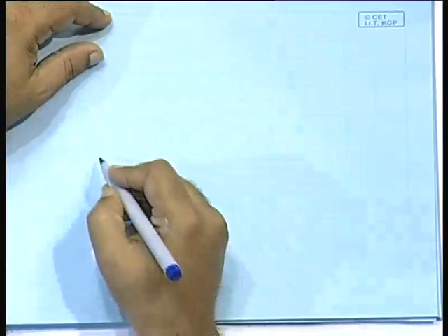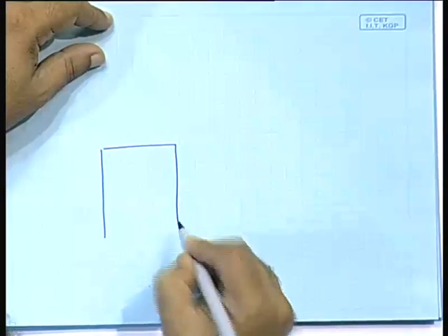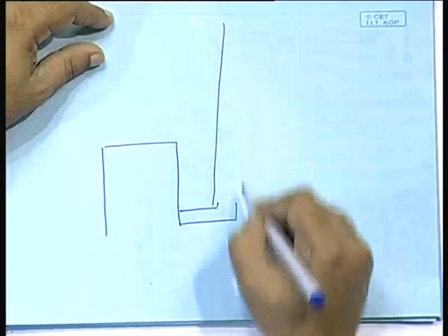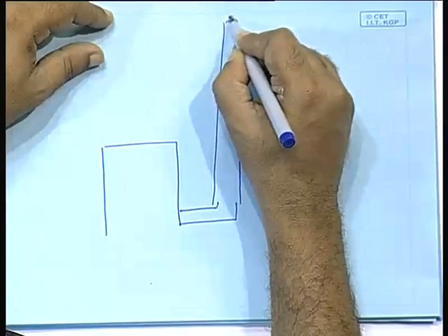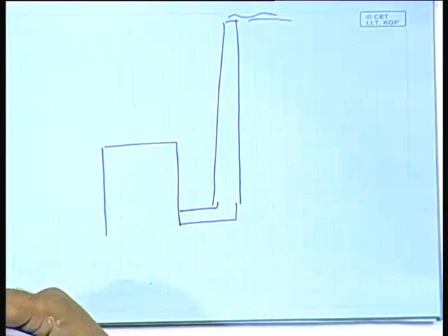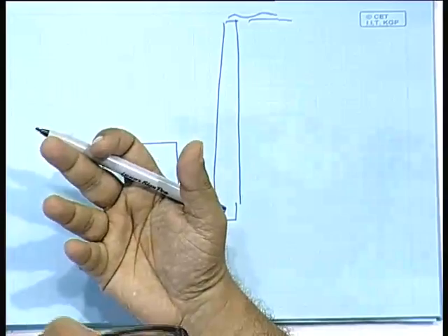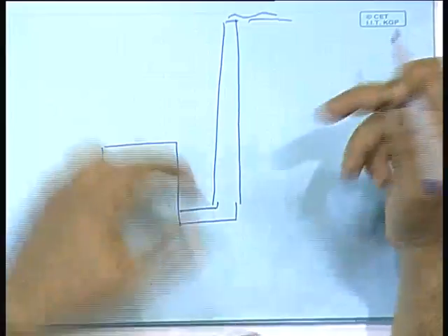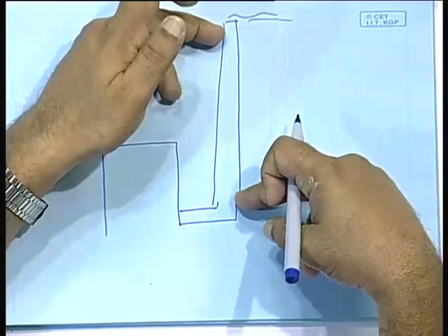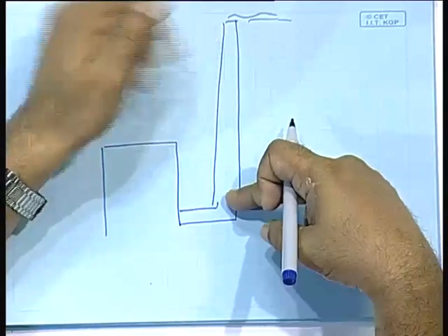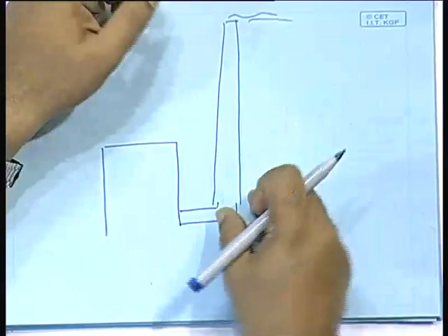So, imagine that you have a power plant here, and then it goes out to a long chimney, and finally it goes out like this. Why should it go up? It has to go up by some kind of pressure difference, else why should it go up? And the pressure difference can be created only if there is a temperature difference, right. So, this is one reason why you need to have a temperature here, else there will be no draft.